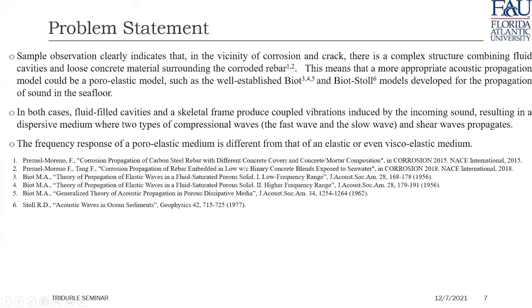Now, sample observation clearly indicates that in the vicinity of corrosion and cracks, there is a complex structure combining fluid cavities and loose concrete materials surrounding the corroded rebar. And that clearly appears if you look at many of these images of corroded concrete.